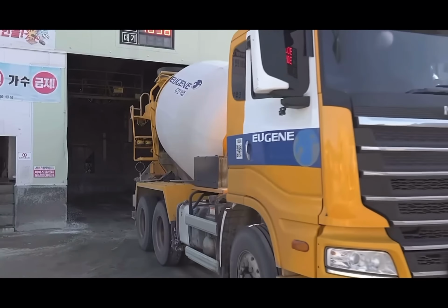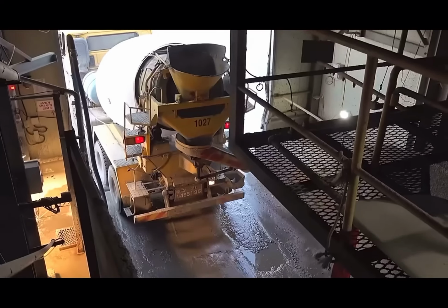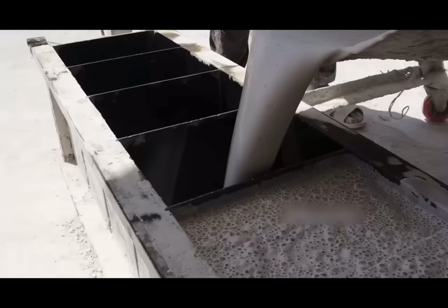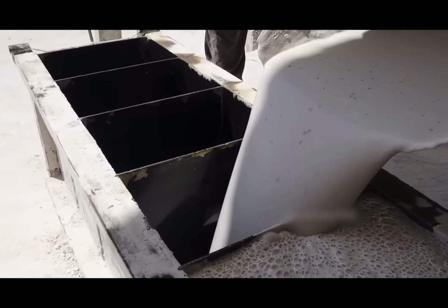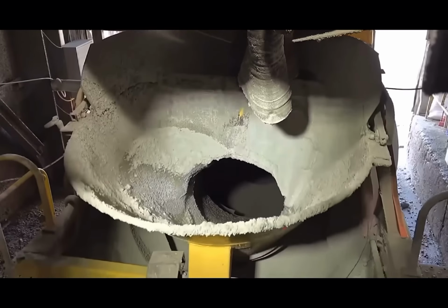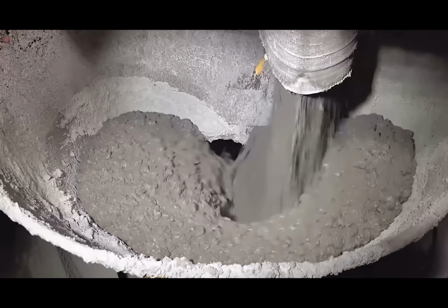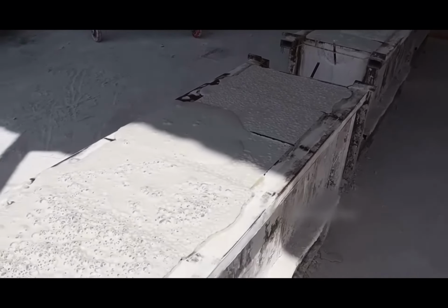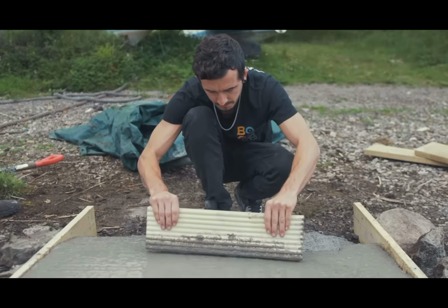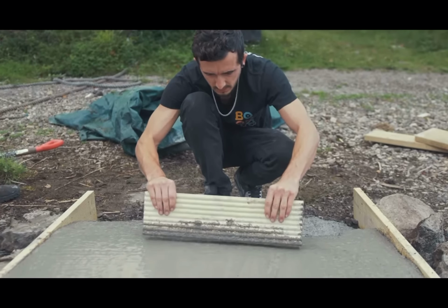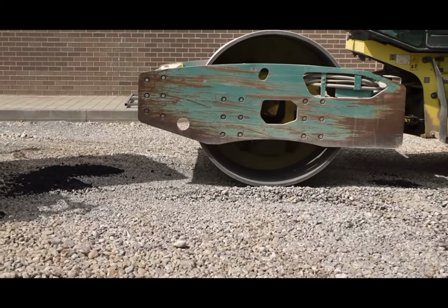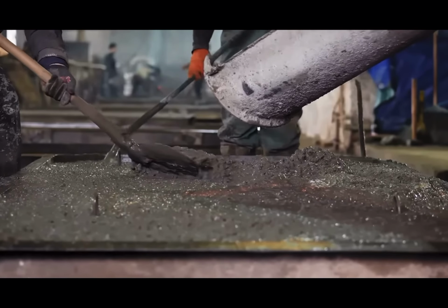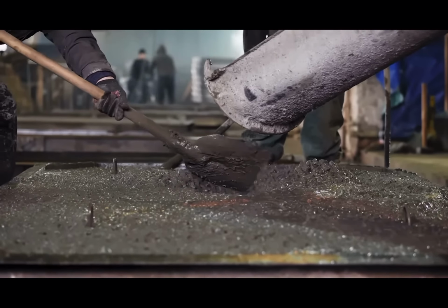Once the concrete is mixed and has the desired consistency, it is transported and placed in its final location. This can be done by pouring it directly into formwork, molds, or by using specialized equipment such as pumps or conveyors. During the placing process, it's important to avoid segregation, which is the separation of coarse aggregates from the rest of the mixture. After the concrete is placed, it needs to be properly compacted to eliminate any voids or air pockets. This is typically achieved using vibrators or by mechanical means such as tamping or rolling. Compaction ensures that the concrete is dense and has good strength and durability.